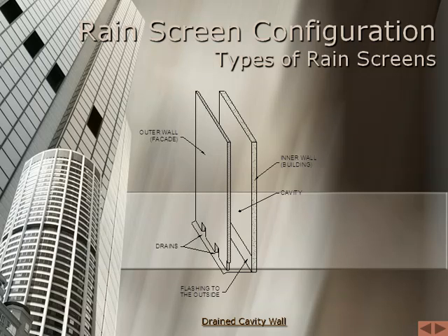In this type of wall, either the outer or the inner layer may act as the air barrier to provide resistance to air leakage. However, the major flaw in this wall design, and what prevents it from acting as a true rainscreen, is its failure to address air pressure gradients. If the outer layer of the wall is most airtight, the wall surface will be subject to significant wind forces. The lower air pressure in the cavity will create suction, causing rainwater to infiltrate through any tiny opening in the building wall surface, whether gaps, joints, cracks, or poorly bonded surfaces.